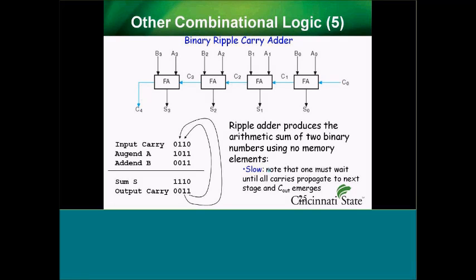Comes through, so that every time this carry goes in, that's the Z from the previous slide, and you add and it kicks it out. So you take each one of these full adders and you build this way. Well, I mean, that's how you build up. And then hierarchically, you go up one more level than this, and those 4 full adders become one 4-bit adder.